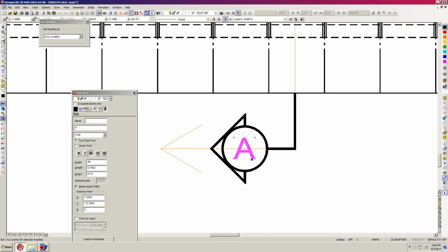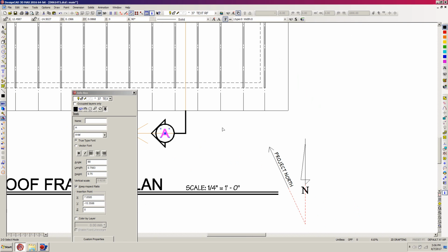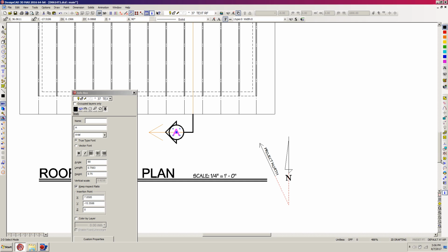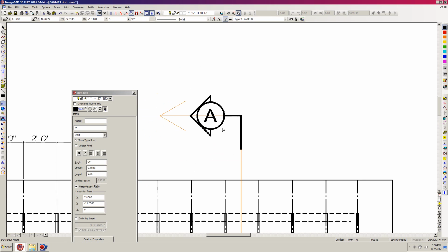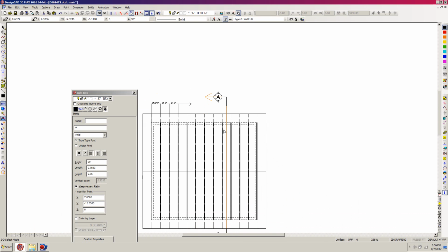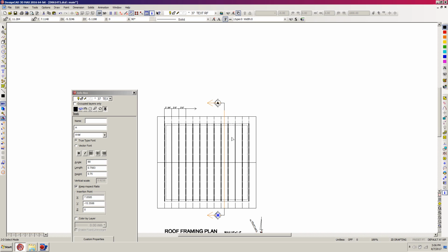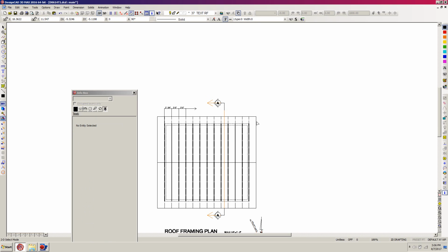Now I'm just going to click the scroll button to set the handle, and now I'm going to hold down Control and use my scroll bar to roll out a little bit, go up to the upper one and hit N, and just right click near the center there. I'm going to zoom up, see what it looks like. It looks fine. So now we have both our layout and our section lines indicated.